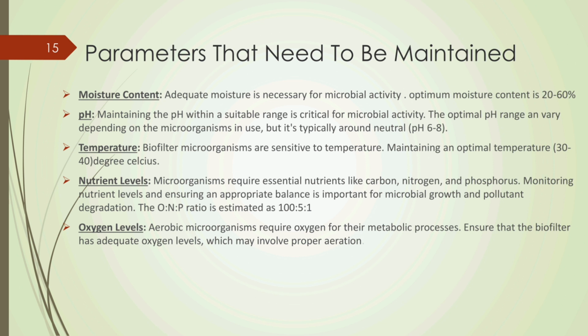The carbon, nitrogen and phosphorus ratio is estimated to be 100:5:1. Oxygen level. Aerobic microorganisms require oxygen for their metabolic process. Ensure that the biofilter has adequate oxygen level, which may involve proper aeration.